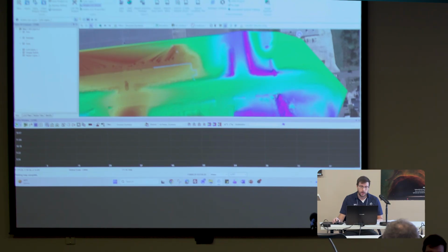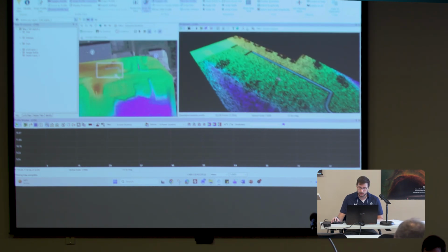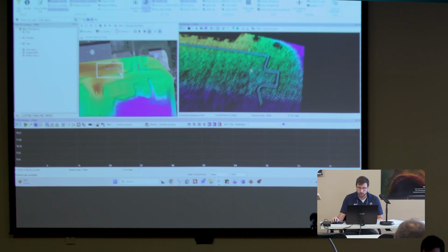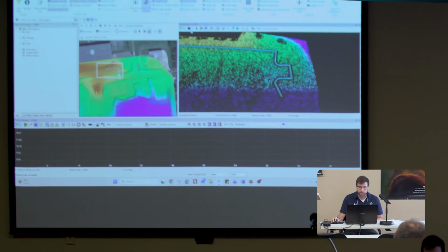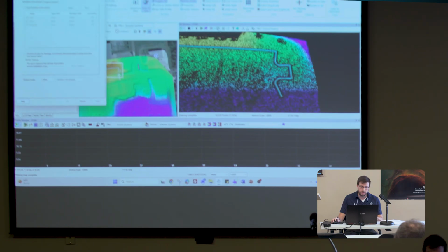And may do something as simple as go to the map view at the top, click on draw 3D view here, and then just look at our different breakline areas. Just make sure, okay, hey, is this looking like we want it to look? Remember yesterday when we were doing breaklines and the day before, here's another Easter egg: do a control left click on the breakline button, and we can go ahead and enforce breaklines.